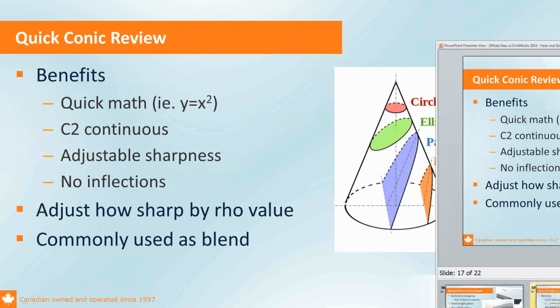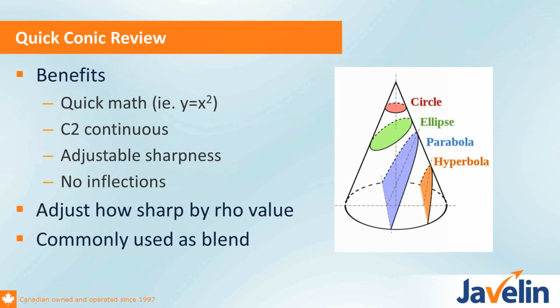So just briefly on Conics, I just wanted to highlight a couple things about the benefits of working with Conics. For those of you who are unfamiliar, they were introduced last year, and essentially it's a curve that's part of a cone, right? So we see a cone there, and you can have any variation of shapes from circles to ellipses, parabolas. It's all those variations depending on the angle. It is fairly simple math for SolidWorks to compute, so that performance can be quite good on those.